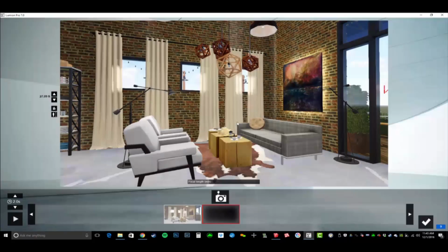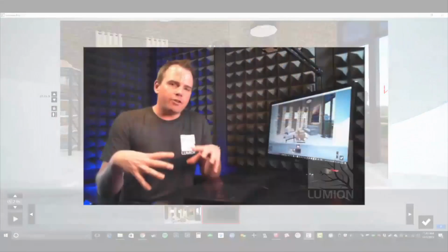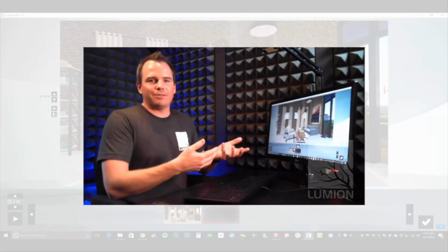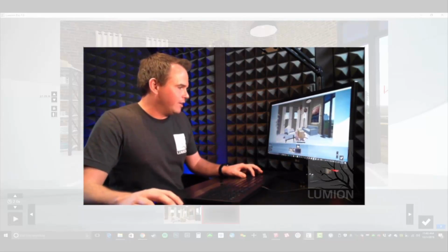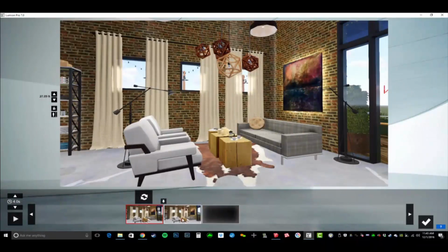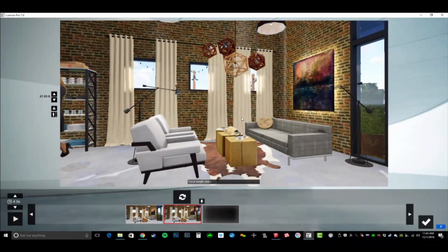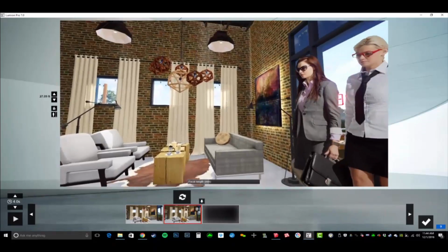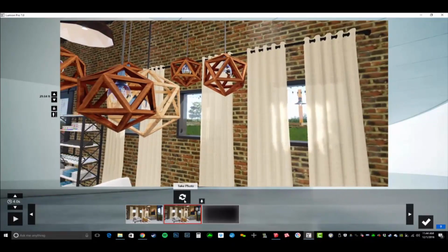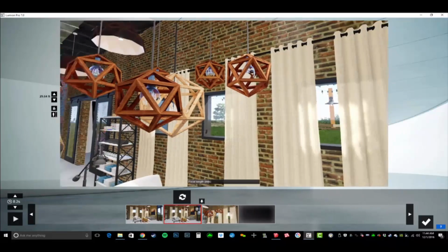So I'll take a photo. One tip on animation, maybe a few tips. First off, slower is better. Lumion renders extremely quickly, so you have the ability to waste some frames. So what I do is start by, see how I went from this frame to this frame? That's how I start a lot of my animations, and that way it gives a slower pause to get started.